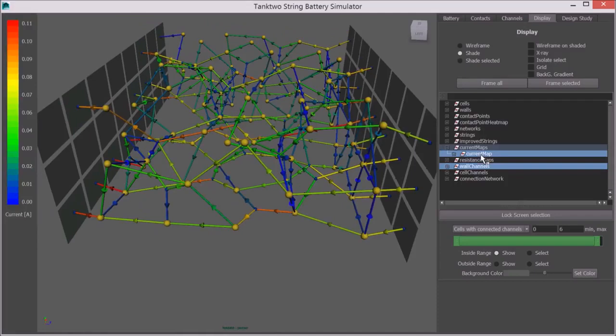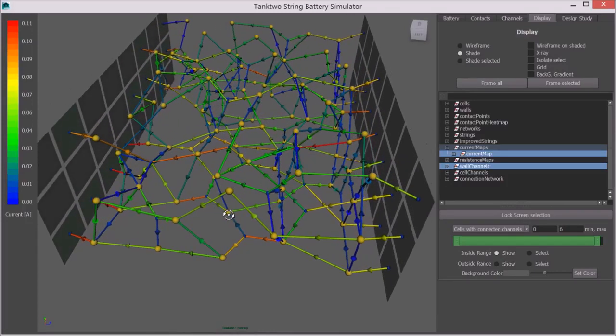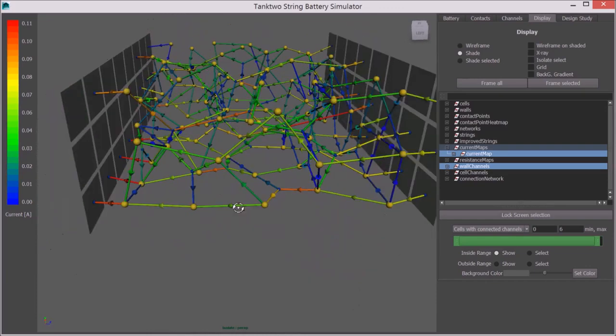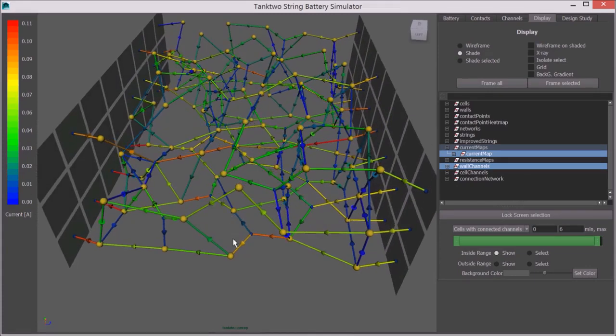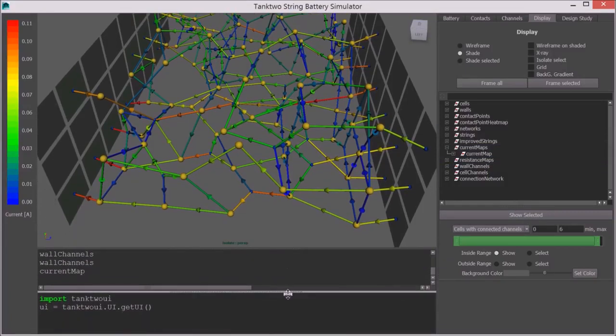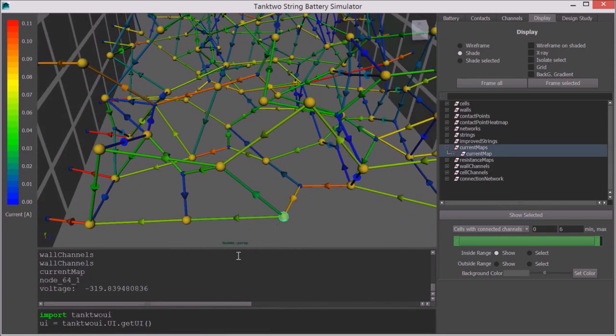This is done by a process where certain wall terminals are connected to current source and rest of them are grounded. To simulate this we need to be able to solve electrical circuit simulations, just like for example SPICE circuit simulator does. Current map here shows presentation of currents through the cell network, while cells are in high impedance mode. At this point let's also open the command prompt and info screen to query some of the currents and voltages. By clicking the nodes or links here, the info screen shows their voltage, current and resistance values.